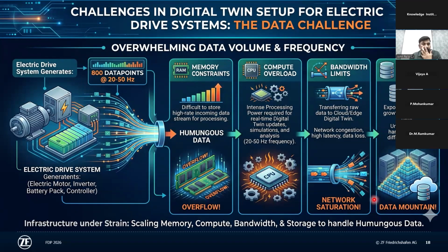For instance, the first bottleneck happens inside the telematics, where the number of CAN interfaces, subsystems, and data points generated by each subsystem is enormous, and this becomes a memory constraint for our telematics. We can't handle that much data bandwidth, and the compute to process this in a telematics box is also too high.